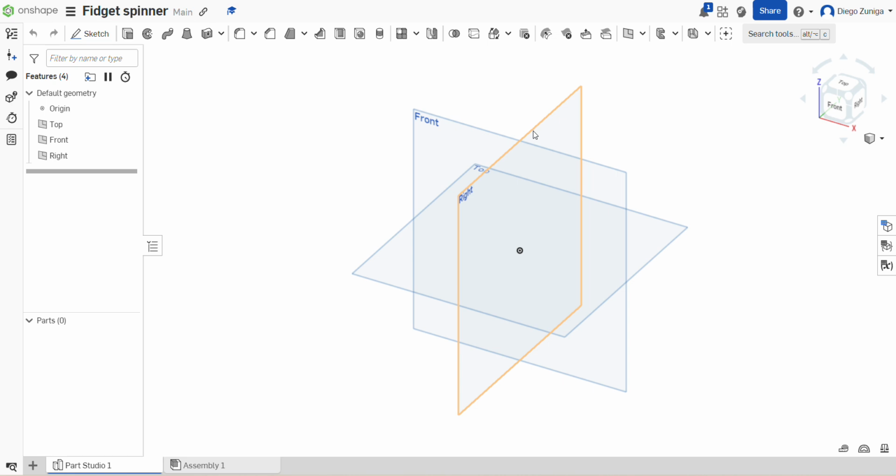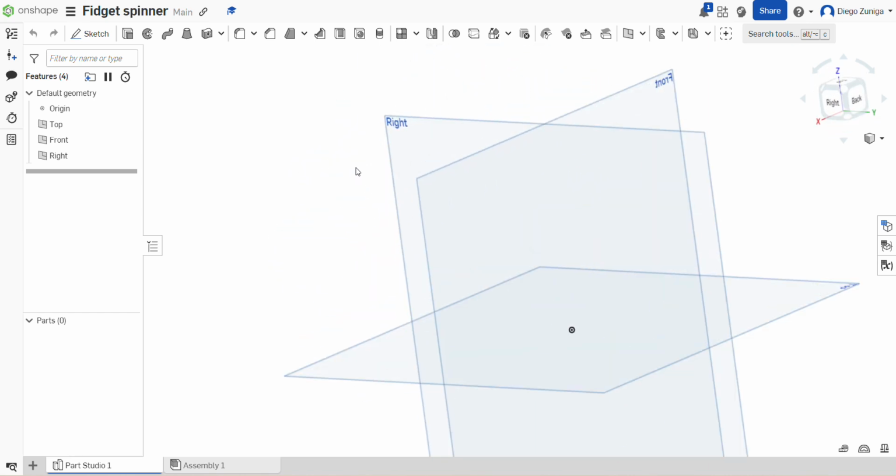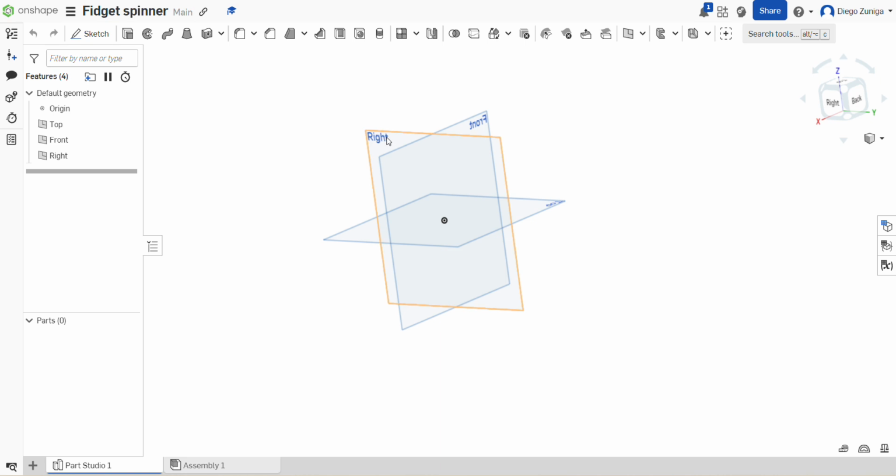And you'll see here that the main tools for Onshape, when we're not drawing sketches, are these, which are ways to create 3D models or to do operations or edits on them. I strongly advise you to use a mouse because with the right click, you can move around, rotating here. With the scroll button, you can zoom in, zoom out. And with the left click, you can select things. If you ever select things and you want to unselect them, you can click on the white void that's around these planes, and you can unselect everything you had.